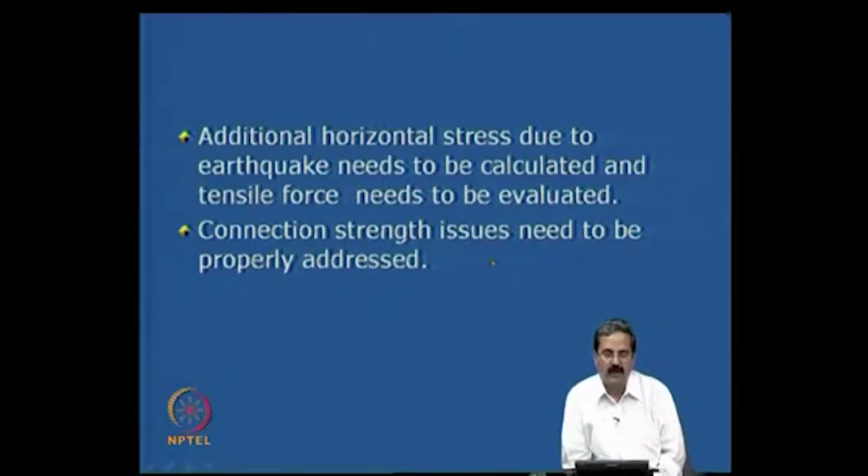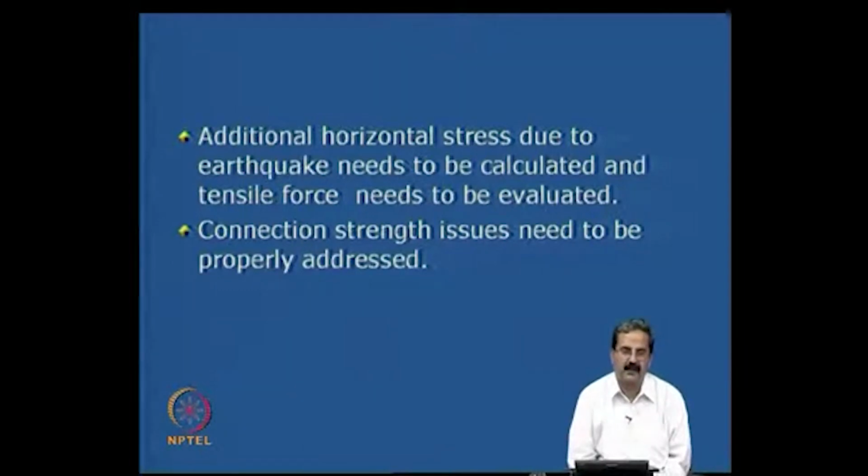So, what we do is calculate the additional horizontal stresses due to earthquake, and even any loading, and then the tensile force needs to be evaluated. That is very important, so that with whatever I just said, you can arrive at a proper geogrid specification. What is its tensile strength? In the design calculations we just discussed, we saw that the tensile force is 1, and then we also have pull out resistance is 1. You can repeat all the calculations, and even back calculate certain designs and see if things are all right.